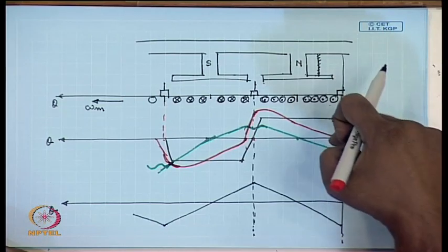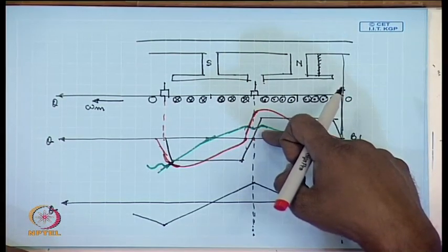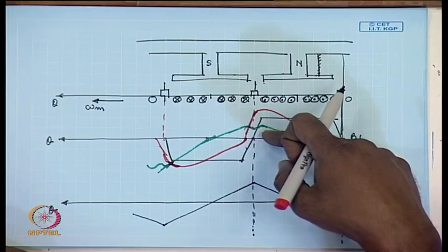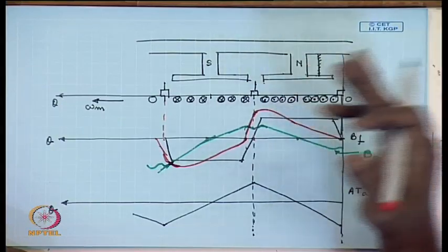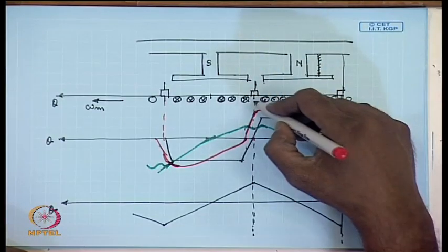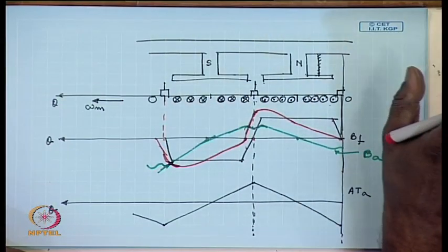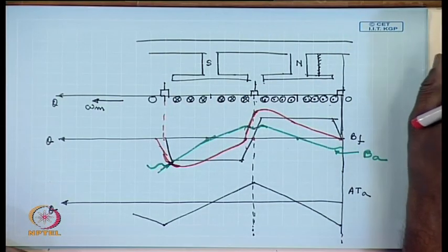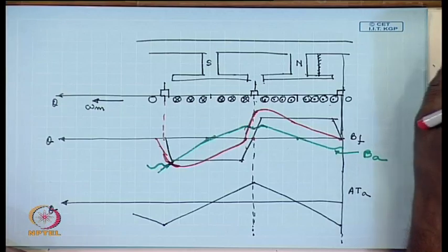Therefore, the armature MMF and hence the armature flux density waveform are also stationary in space. Individual armature coils pass through the brush, but the pattern of dot and cross current between two brushes remains always fixed. So, the armature MMF and the armature flux also remain stationary in space.